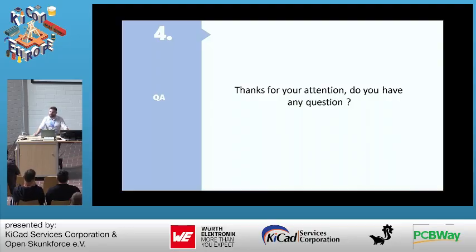And then we will automatically ask you if you agree that we also fill the vias with resin, but you have to know that it will create some additional charges. If you don't want us to put resin inside, you have the issues that applying the solder paste can create. That's it. Then your second question was about side plating. No, it's not possible. All right. Thank you very much.